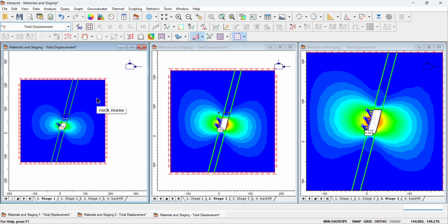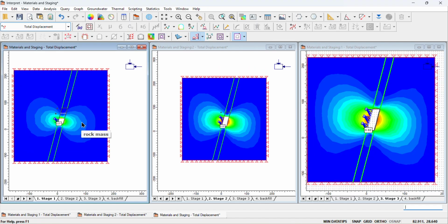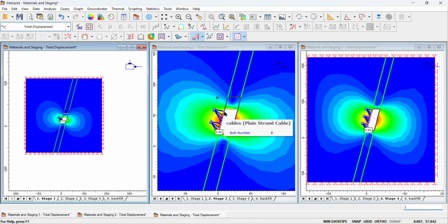The next step is I want to study deformation boundaries here. This is the boundary now. This is the tunnel excavation, stage 1, stage 2. There are 3 stages of excavation. Here you can see this is the boundary. So we have to study the boundary deformations towards the opening, how the deformation is occurring towards the opening.